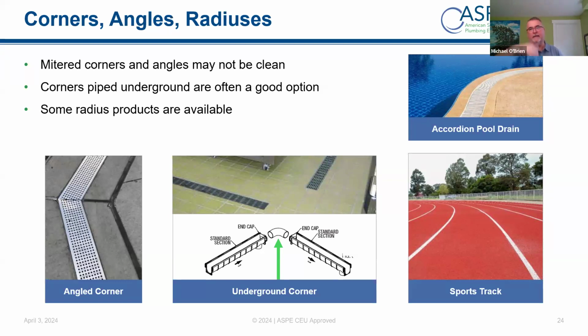So as the sand enters into the bucket, it settles on the bottom and the water overflows and drains out. It's not a difficult thing to do, but on a 24 by 24, that could collect a lot of sand before you're lifting it out.